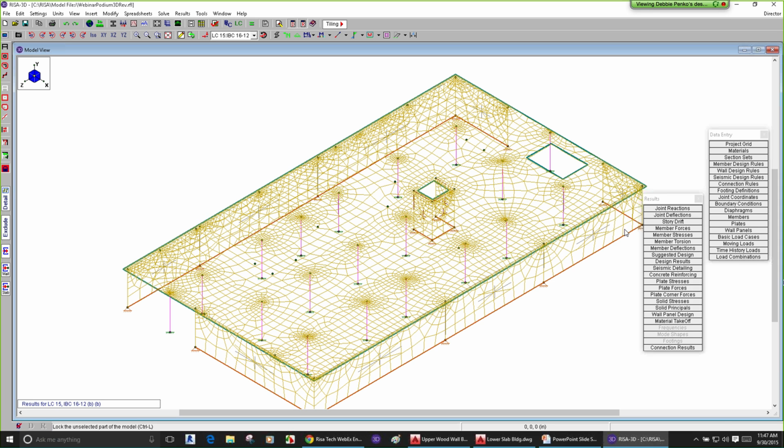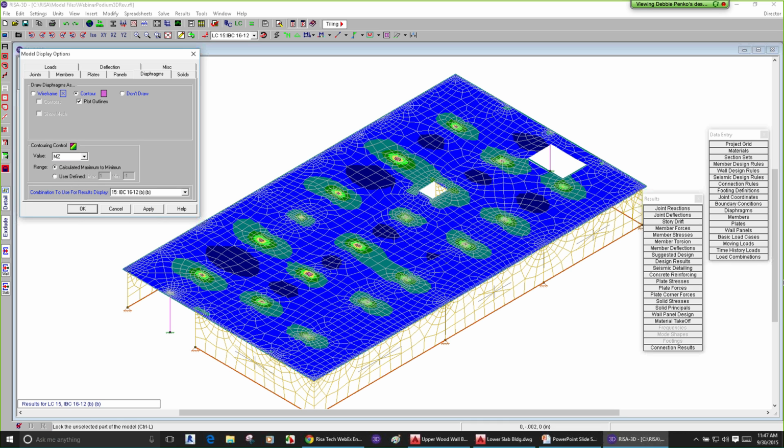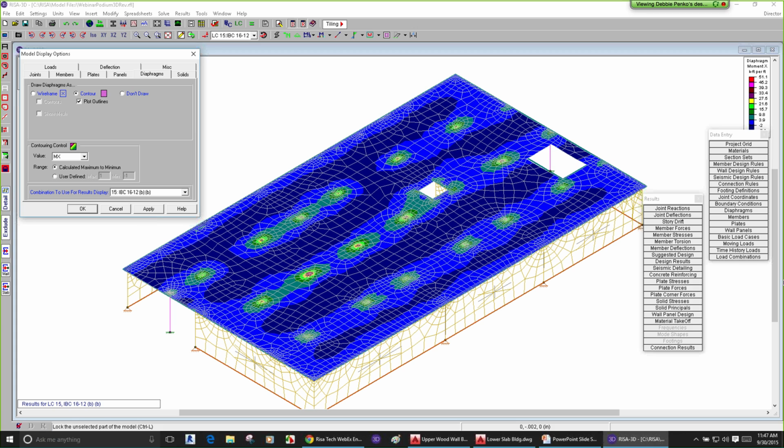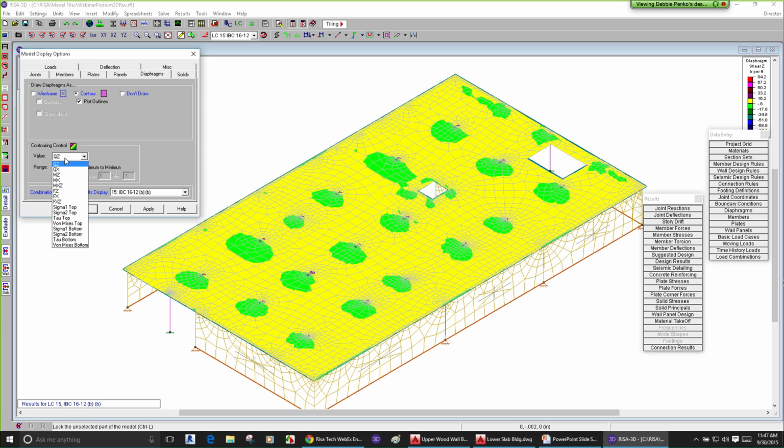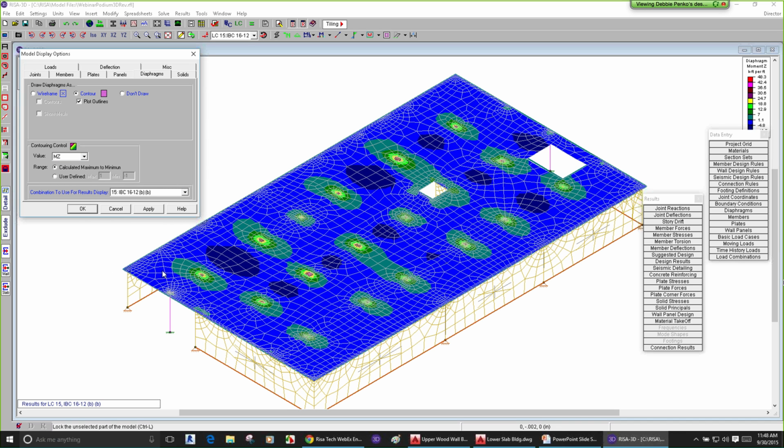The other piece to find out in here, you can turn on our contours to understand that slab. So in the diaphragm, we can look at how the forces are being distributed, maybe look at the moments. And we can see exactly what kind of the similar stuff we saw for gravity, but this is actually showing it as we apply some lateral loads. So if you ever needed to worry about designing that in any way, lots of times people for semi-rigid diaphragms don't really design it to take that lateral force, but you can, as you see the moments and shears through the structure, if that is part of your lateral resisting system and you need it to take those.